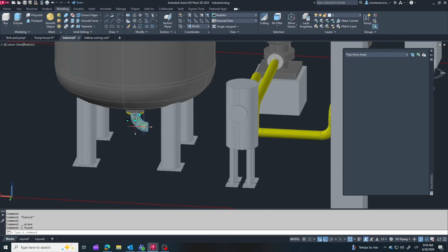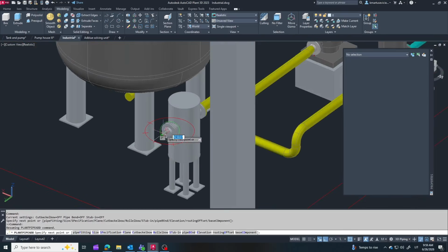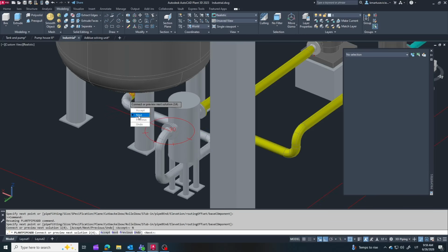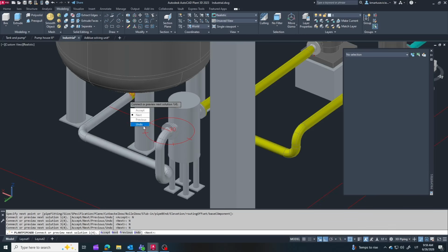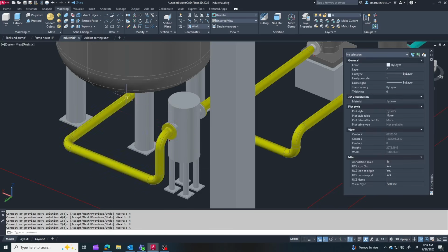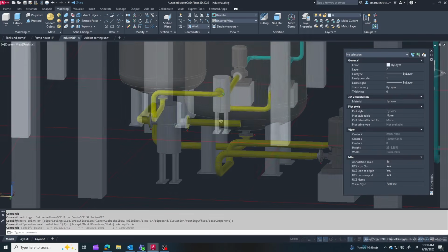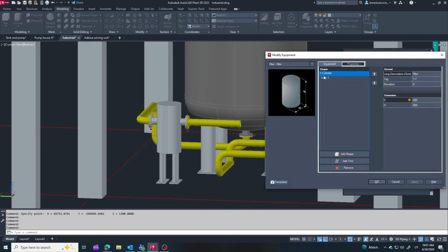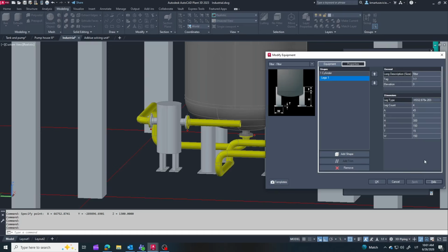This is one of my favorite parts of the design process. Every time I add a new piece of equipment, I need to find the best location for it and then think about the simplest and most practical pipe routing. At the same time, I always consider maintenance. The equipment should be easy to access, operate, and service without unnecessary obstacles.